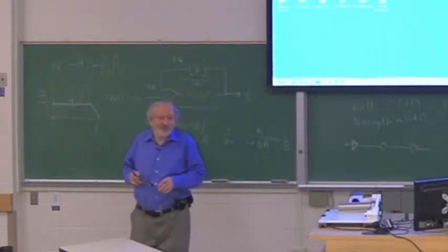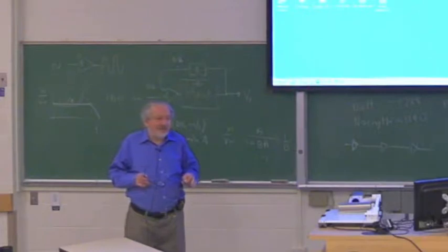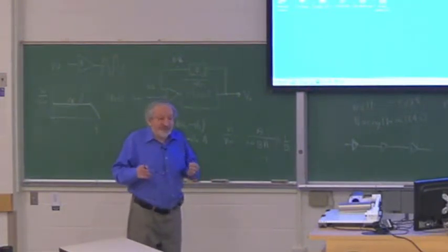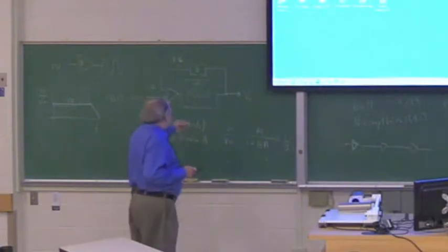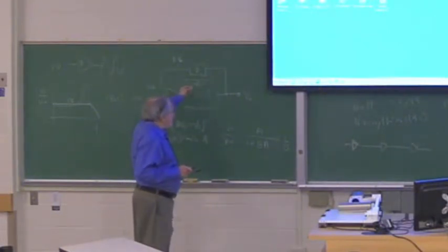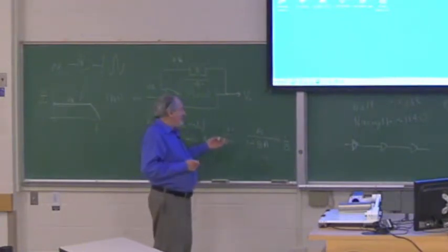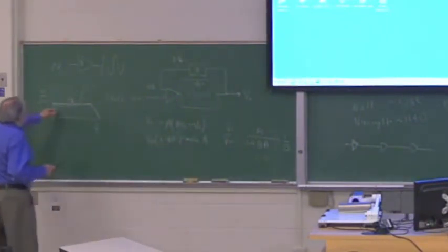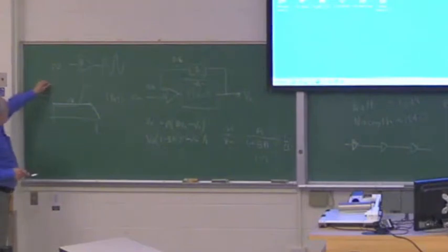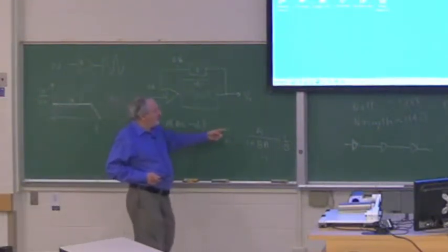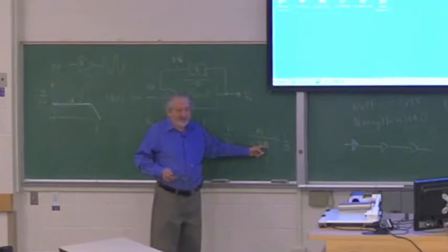And his bosses said, it's a very bad idea. He said, you are saying instead of making an amplifier with a gain of 100, we should make an amplifier with a gain of 10,000 and then throw away 99% of the gain. Because that's what you do, in a sense. If this is a graph, the open loop gain is very high, but when you put feedback in, you throw most of this gain away. But you throw it away to make the system independent of the gain, right?